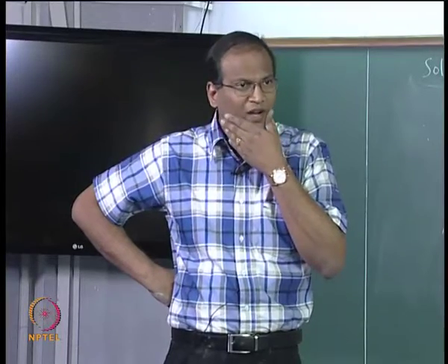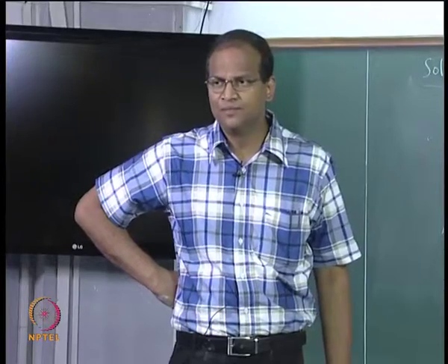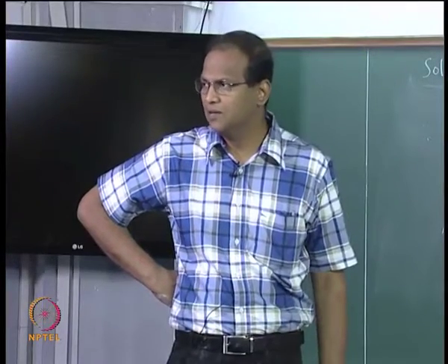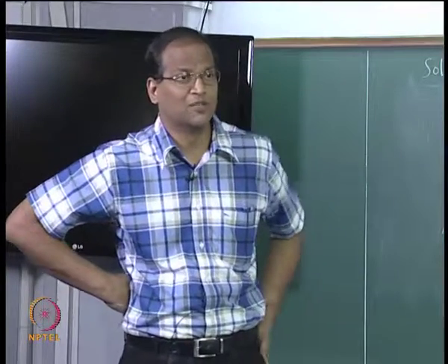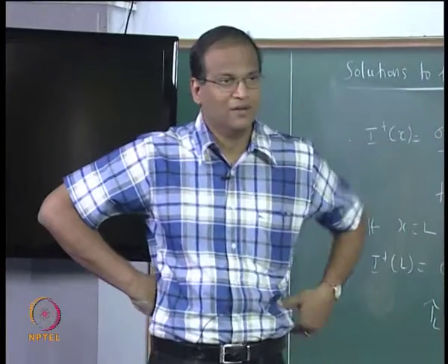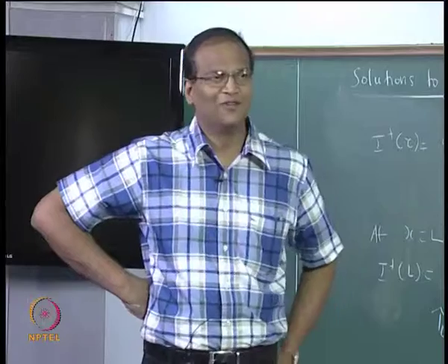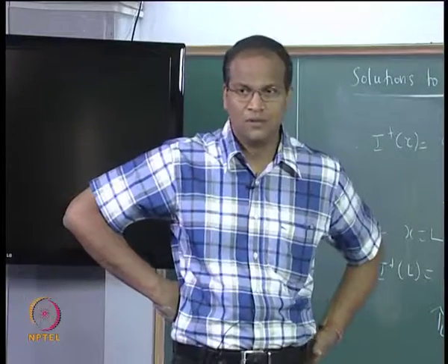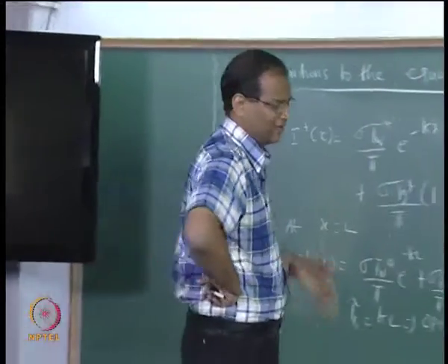And also, did you study fin heat transfer? If you have a variable fin area, you will get the cos theta frequently. Cos theta comes frequently in several areas of radiation heat transfer. I am not sure about stress analysis and all that. Cos theta is an important fellow in many walks of life. Therefore, you treat cos theta as mu, and therefore sin theta d theta can be treated as minus d mu.